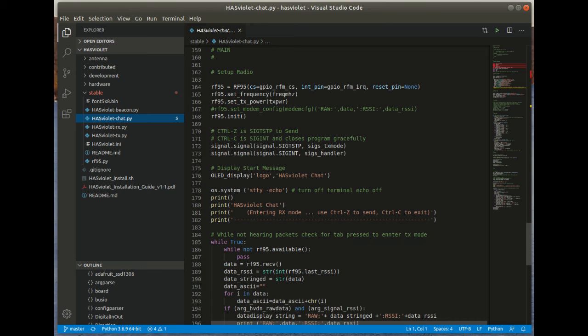because the challenge is this: there is no buffer coming in from the Adafruit module to the user's program space. There's no hardware buffer. In fact, you would need a hardware buffer to queue up anything that's being signaled to run all the various other subroutines you want. So we actually have to always be in receive mode and use a signal to cut us out to send something we want to transmit, and then jump back into the loops again.